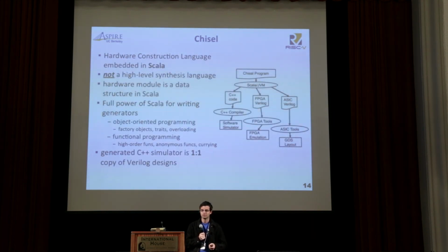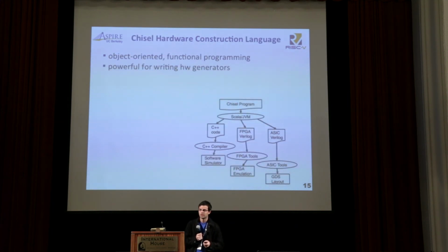This is really, really awesome for my productivity. And Chisel, I think, has helped sell this pretty well. For me, this allows me to describe very highly parameterized designs. As an example, I was trying to run SPECint, and I found out that SPECint has a lot of floating point in it. I didn't expect that. It turns out that even if only 1% of the program is floating point, but it takes 100 instructions to implement a single floating point instruction, that means half your time is spent doing floating point.